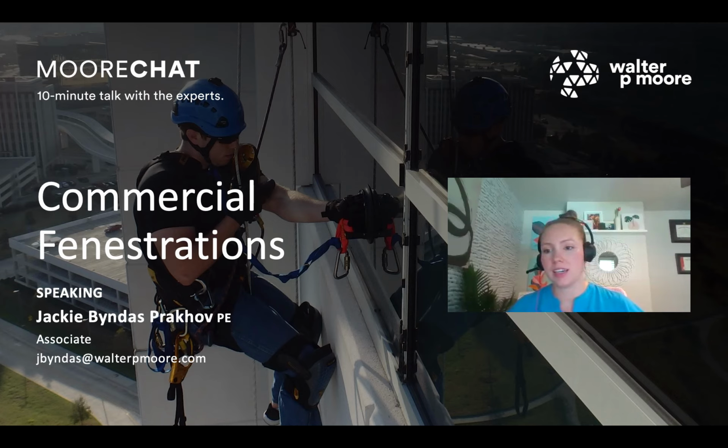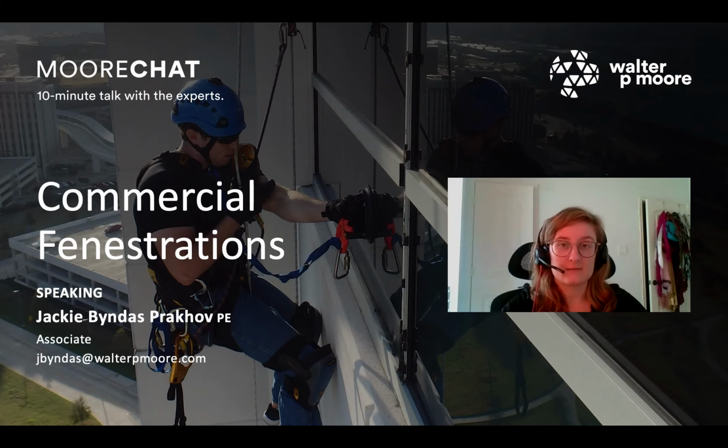One of the questions that I had just watching your presentation: what is the most common detailing issue that you come across for fenestration systems, particularly in the design phase? So in the design phase, a lot of times I will review architectural details, and the 2 most common mistakes that I can see are that the air water resistive barrier does not connect to the air seal, and also the head flashing is not positively lapped. So instead of water being directed out in front of the head flashing, you have a seam where they're reverse lapped and can possibly be a point of vulnerability.